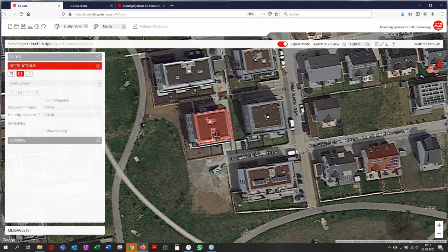Tiny little obstacle. As you can see, the first line is always parallel to the roof, and it jumps rectangularly. And when I don't want to have that, when I really want to have a diagonal or not a parallel line obstacle, then I push the shift button on my keyboard.